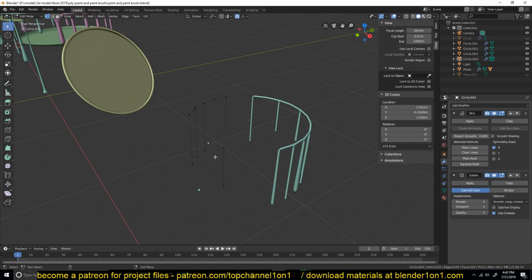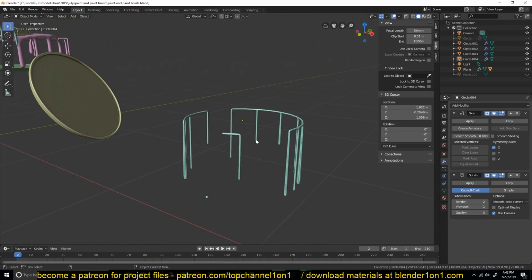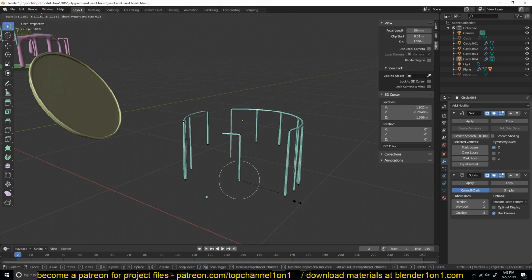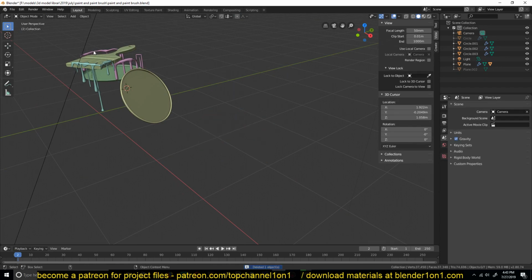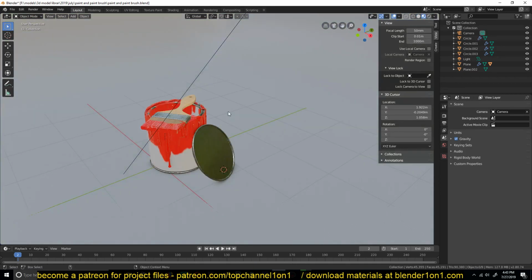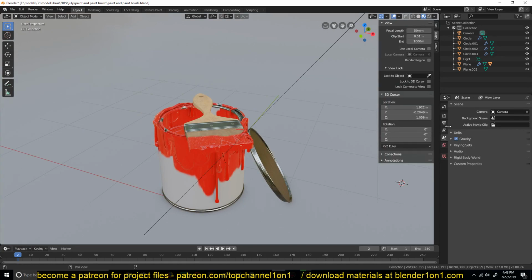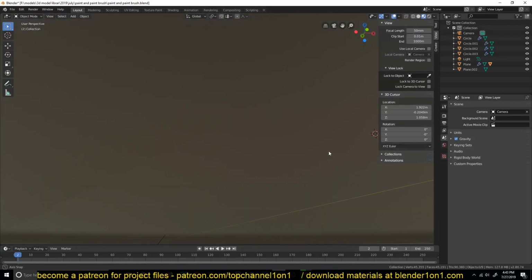So you just select any of the vertices and then mark root and give it its own volume, like that, in case it's missing it. So any part of the mesh that is disconnected, you need to give it its own root after disconnecting, and then you can do whatever you want. So I recommend you go watch the time lapse to see all the tricks that I used to achieve this paint effect, including the texturing. You can see we even have a little bit more details in different areas.